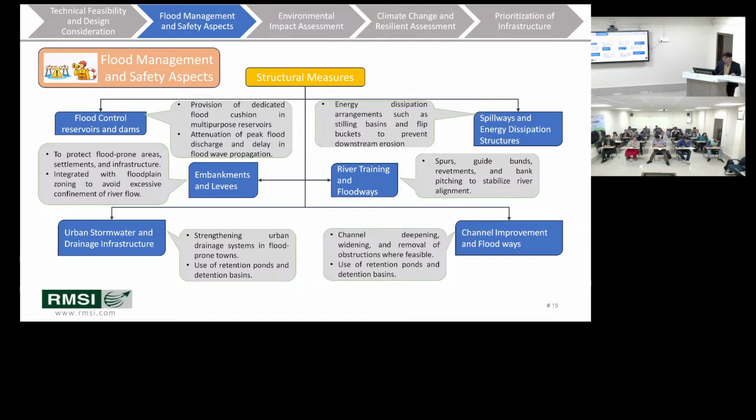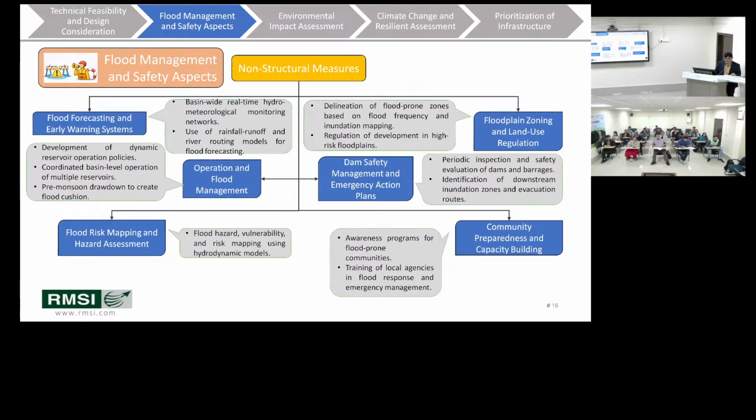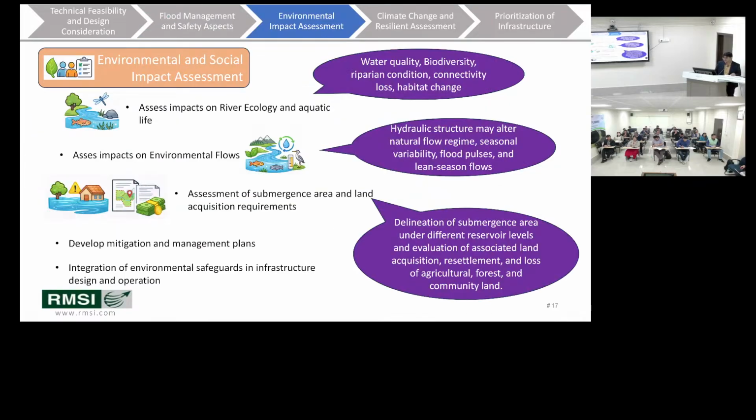Then we have already discussed those structural and non-structural measures: flood control, reservoir spillways, river trainings, embankments, levees, channel improvements, urban stormwater drainage. Then non-structural measures, as we already discussed in the last session, you should have the assessment of all this existing information in your basin.